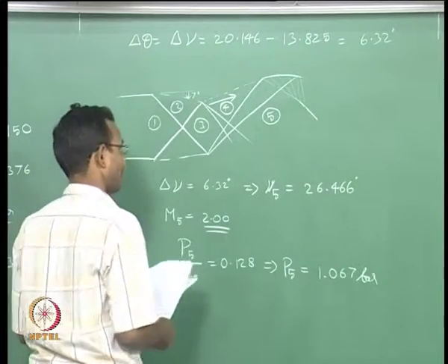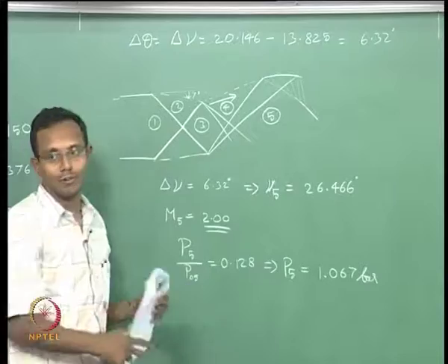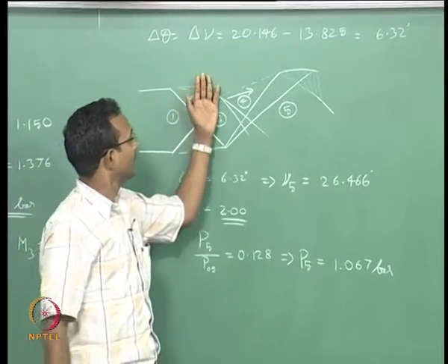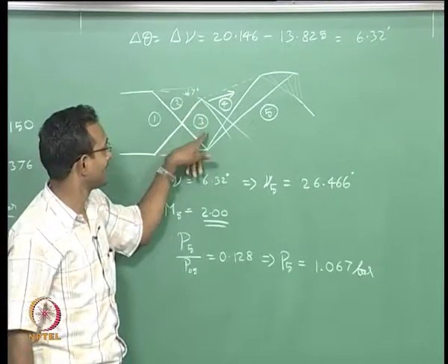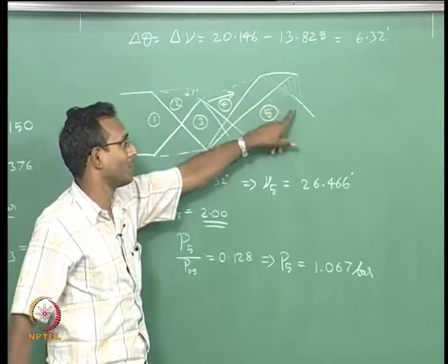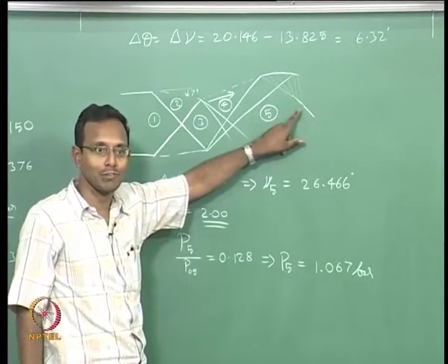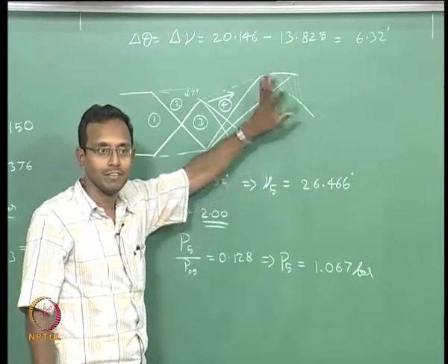Okay. So, this same process I can follow if I want an under expanded jet, which will start like this. Exit pressure will be like 3, condition 3. From here I will just go and I will suddenly say I cannot go past this point currently. I do not know how to solve for compression waves coming together and forming a shock. We will leave it there for now.